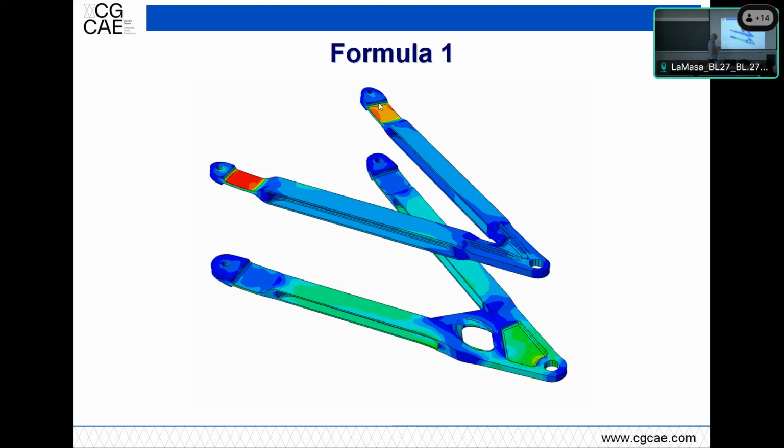In the mid-90s, something like that, John Barnard, who has also been a designer for Ferrari, invented this system. So instead of having the ball joints, he said, why don't we put flexible elements? They're called flexures. So here we have a normal, strong bolt, so we don't have the ball joint, and we do have those things, at least on the input side. The connection to the upright is still done with ball joints, but you get rid of some of those compliances.